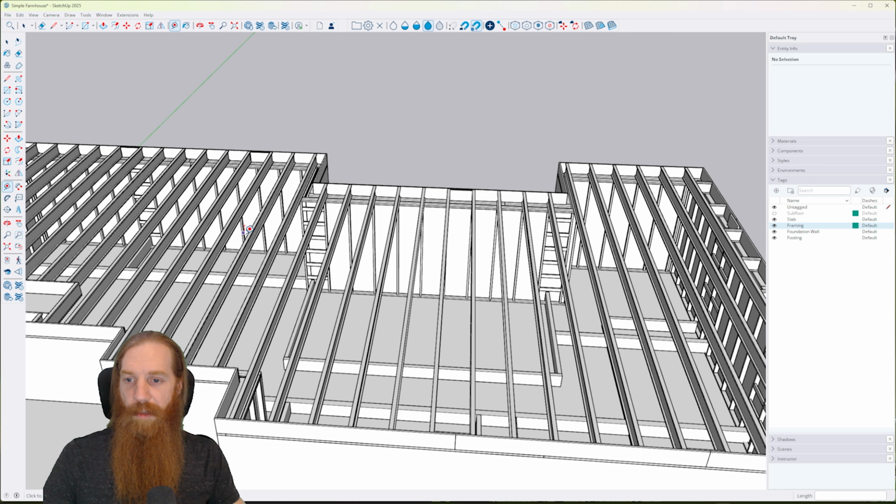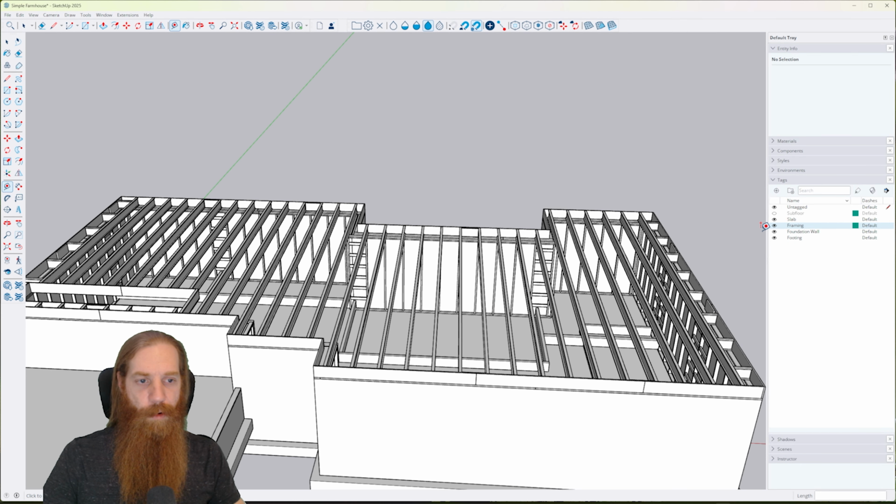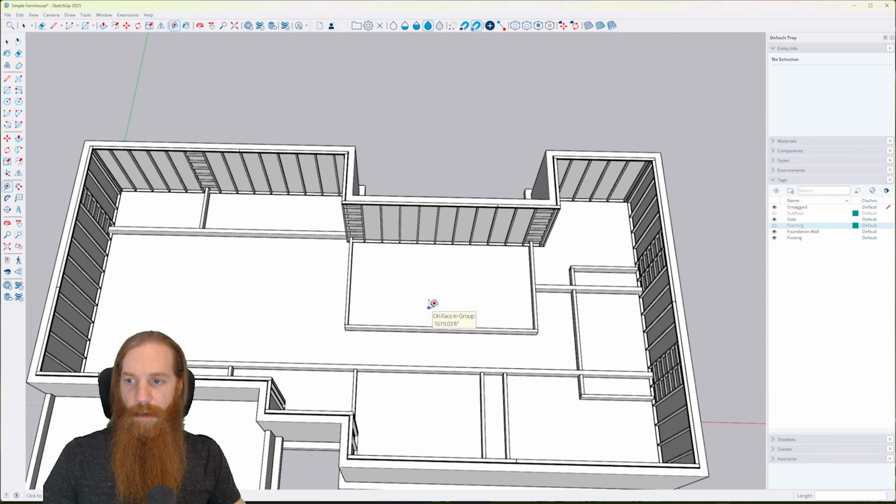But for a simple little rental like this, there's not really going to be a lot of duct work or anything in particular that we need the extra space in the floor trusses to utilize. So we're just gonna go with the standard I-joist here. Works perfectly well. And for a rental, that would be my preferred method, since that is going to be the cheaper option.